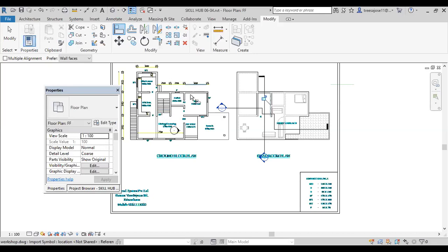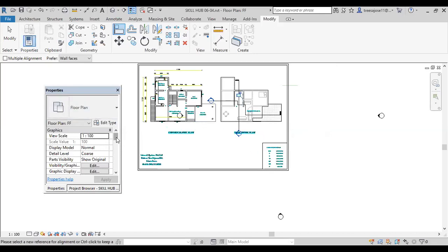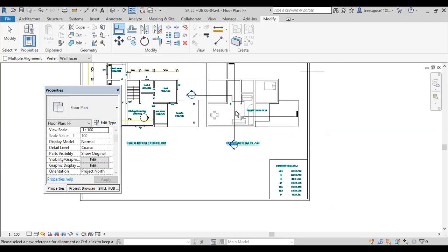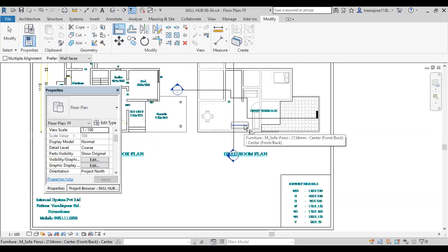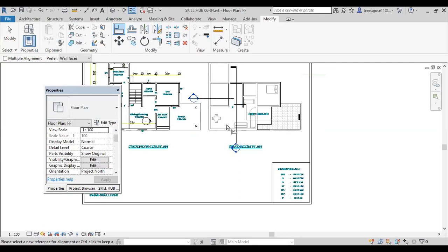Then I think it is better you close it. If you wish, you can turn off the underlay and finish the work. Then you finish the first floor. This is the procedure to align that one. In the case of multiple floors, you just select the AutoCAD image and move it into the corresponding level. After that, take any reference and align that to the particular level. Then automatically you can create the drawings.